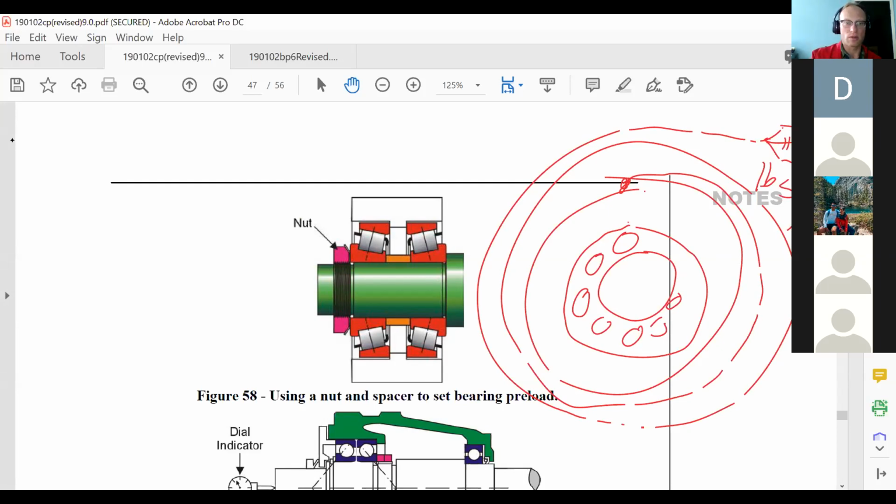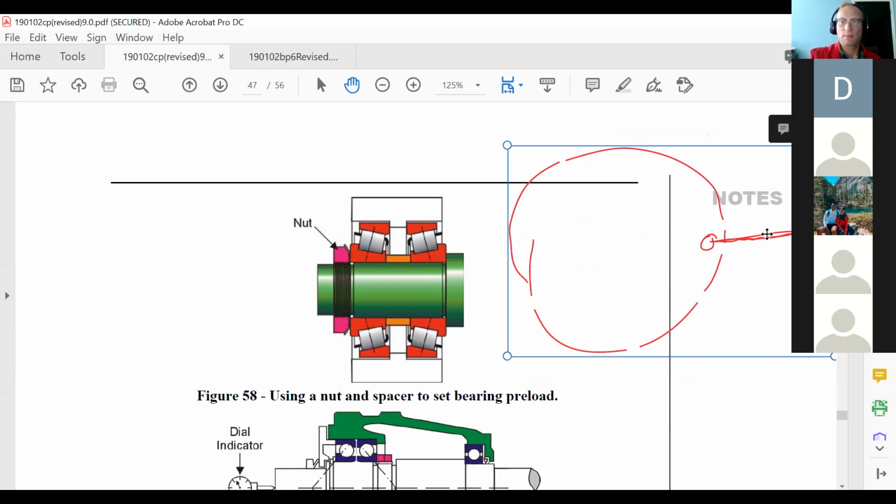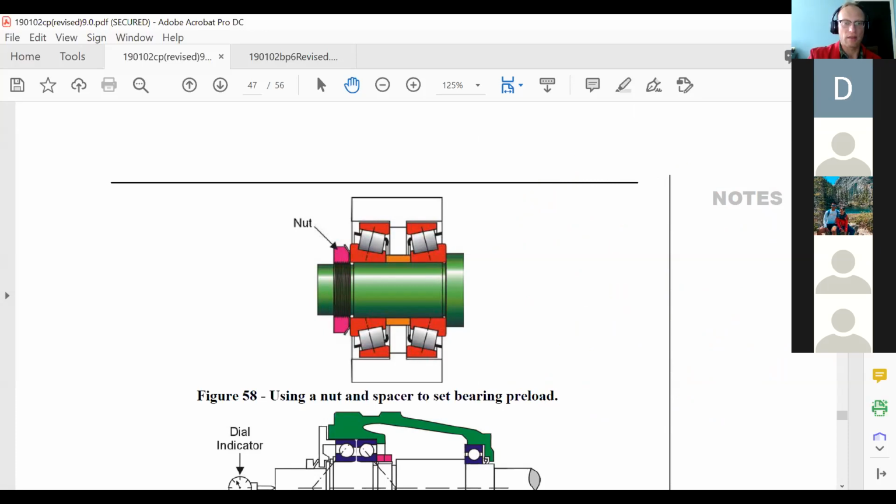And that is the measurement of preload. In some instances, you'll also use torque. So for instance, if I yet again have this turned sideways, and I put a torque wrench of a known value and known reading on here, I can find out if the preload is set correctly. Typically, it'll be that fish scale method.